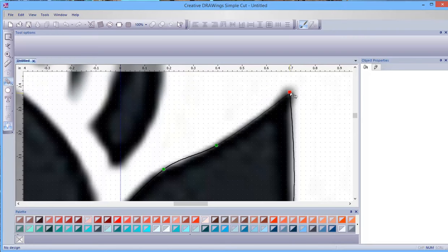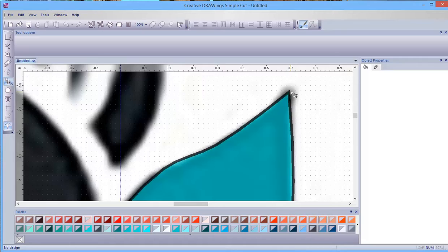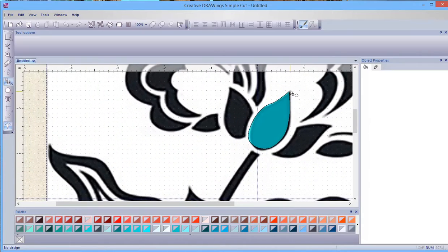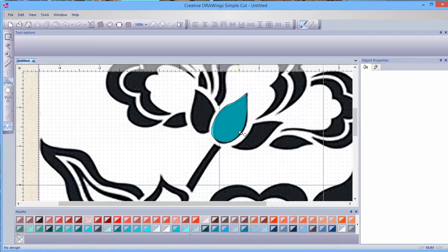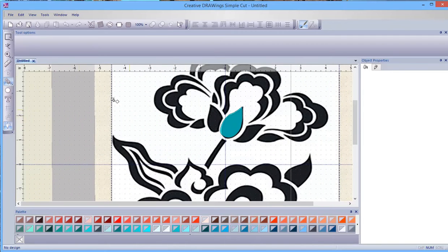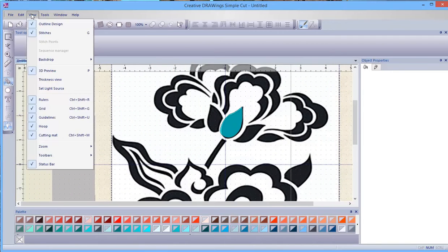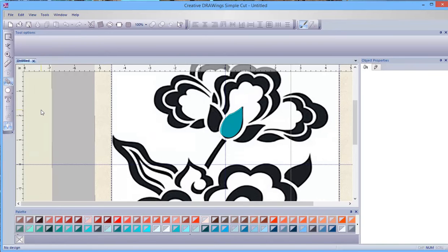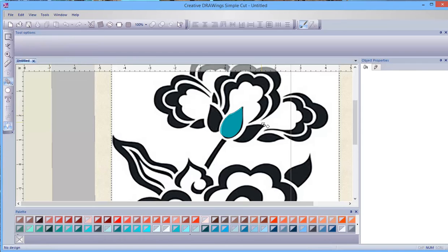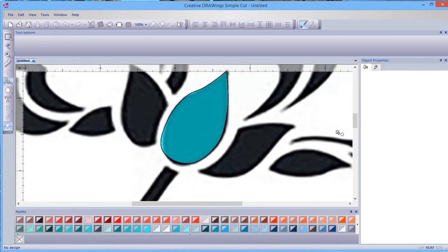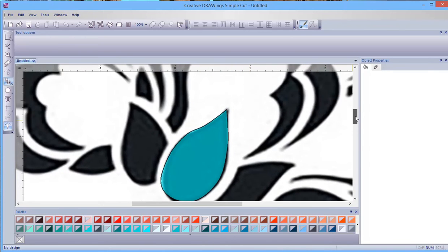And then when we get back to the beginning here, we're just going to hold down our click on our mouse. So that's our left hand click, and that will create our shape. So what I'm going to do is I'm going to come up here and I'm going to turn some of this information off. So we've got rid of our grid, and we're going to get rid of our grid lines. There we go. So that just helps our mouse focus on the places we want to create our cuts.